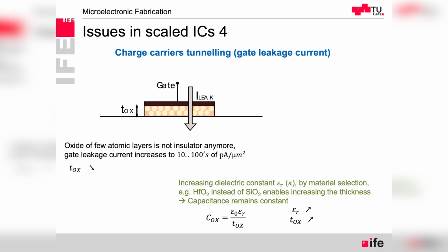introducing new type of the gate oxide material. So rather than the silicon dioxide, it's hafnium dioxide, or there are also other materials, something I think also including zirconium, but I haven't included all the details. These materials are so-called high K, because kappa is also used as a symbol for dielectric constant, so high K, at the same time metal gate. That's why we call these technologies HKMG, high K metal gate.